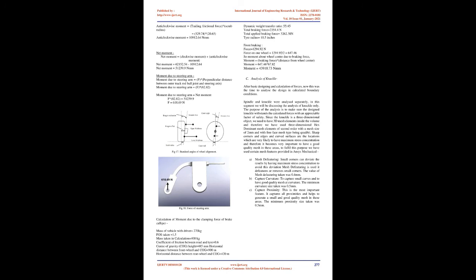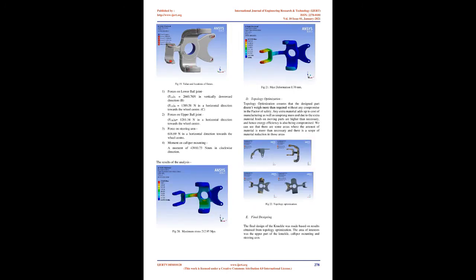We have considered a case when the vehicle goes over a bump and the wheel reaches its maximum travel. In this position, the damper compresses completely and the suspension arms rotate to their maximum. In that instant we can assume the whole assembly to be in static equilibrium. We have used Fox Float 3 and referred to its manual for calculating force at maximum compression, which is 5,700 N for 4 inches of longitudinal travel.